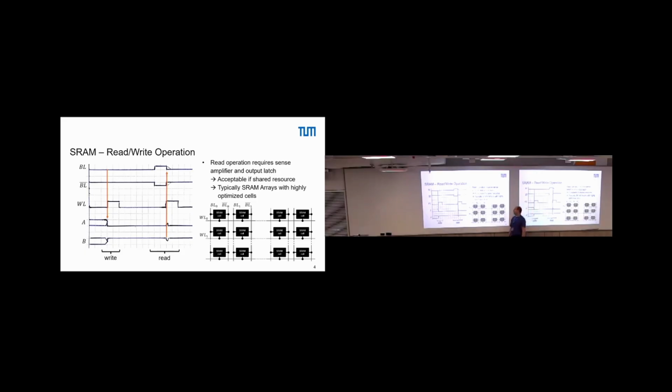If it's a 64-bit system, then most likely the SRAM in there has a word width of 64 bits. So it can fully parallel read out 64 bits and put them somewhere else where I want to process them. That is why we have these in parallel. If you have a 32-bit system, then your SRAM is most likely 32 bits wide. So the word line enables which word we want to read. The bit lines always go to this sense amplifier and a subsequent register.